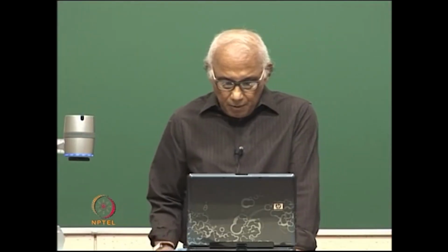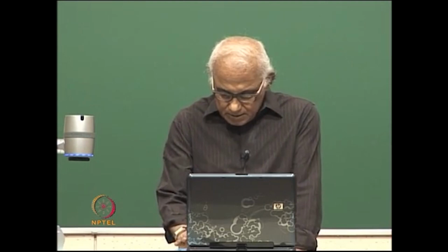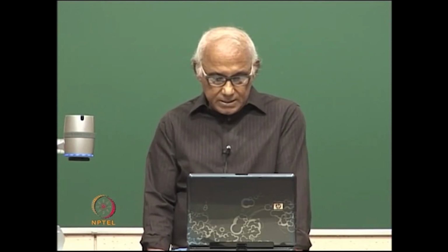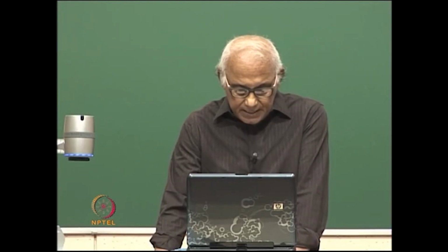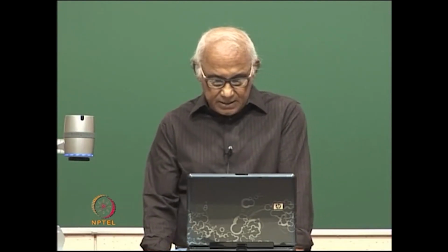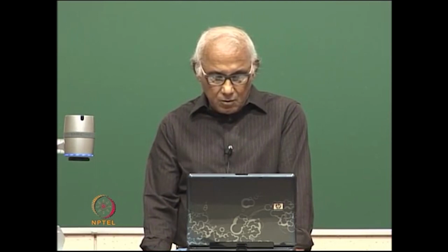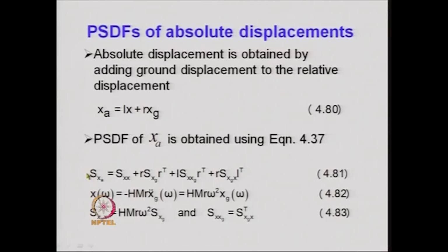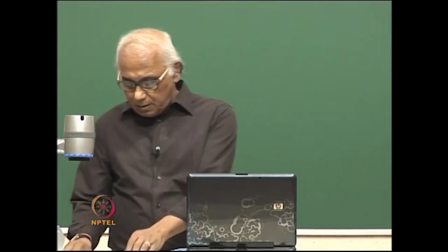So, with the help of these relationships, once we know Sxgx and Sxg, one can obtain the value of the power spectral density function matrix of the absolute displacement. So, we stop at this, we will solve a problem in the next class.